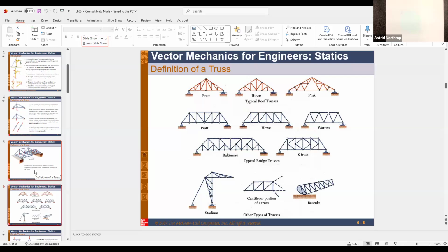All of them are built on triangles. If you look at the basic shape that you add on to, everything is a triangle. You start with a triangle, add structural members that again form a triangle. So in other words, a truss is very particular. What a truss does is it distributes a load and prevents things from collapsing.